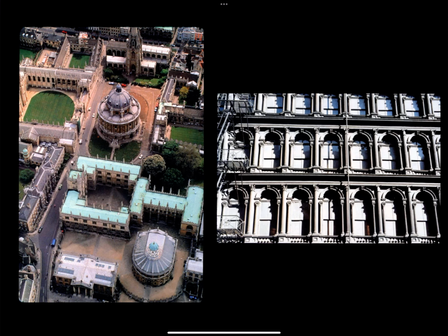Also, during the past 150 years or so, metal has been used as a substitute for stone. So we talked about this right at the beginning of the semester when we talked about cast iron facades, which you see on the right. In this case, molten iron would have been poured into molds to make manufactured, mass-produced cladding. So the molds were reusable, could be used over and over again. And this is a non-structural skin.